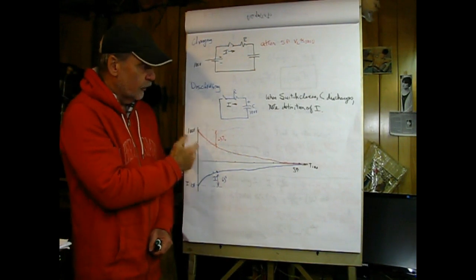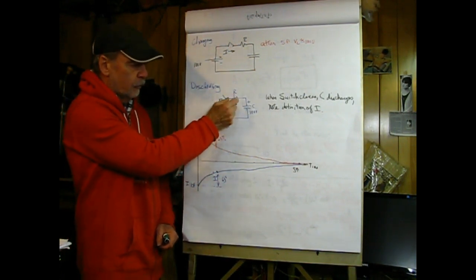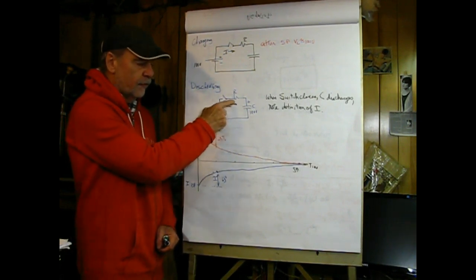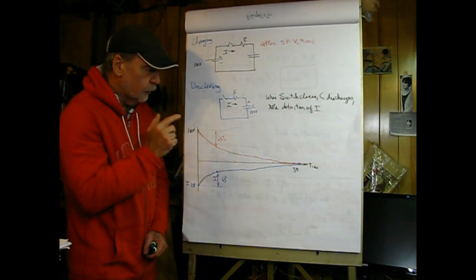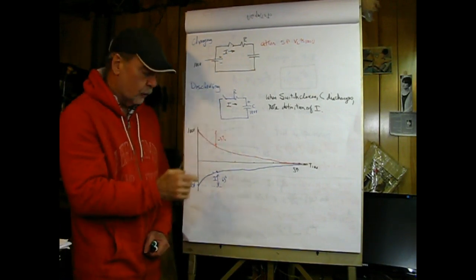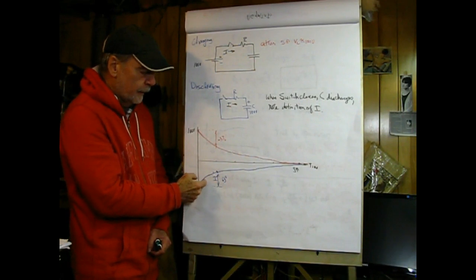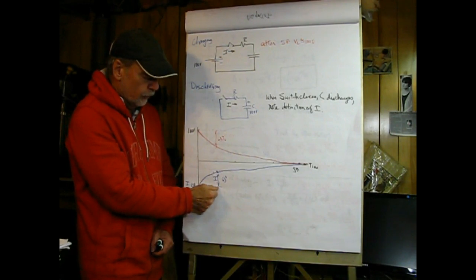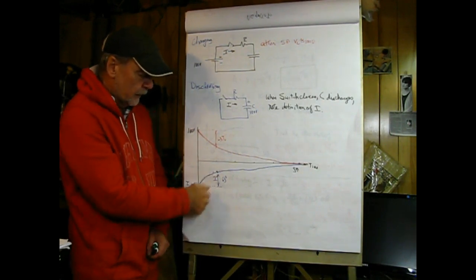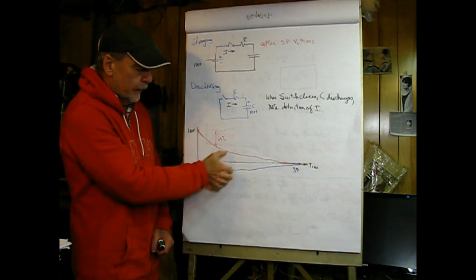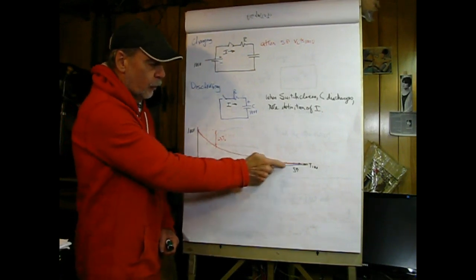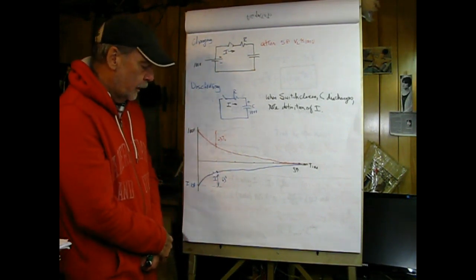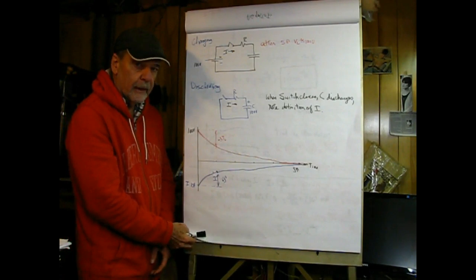Now the current, when it starts out here, is, since we have 10 volts across the resistor, going to be a maximum of 10 amperes. But since it's flowing physically in the opposite direction to the defined current direction, it's going to be negative, and then it decays exponentially, again 63% from the initial value of 10 amperes down to our 1 time constant value. And that would occur for time constant 2, 3, 4, and then at 5 we would say that the current is 0 by industry standards, and the capacitor voltage is 0 again by industry standards.